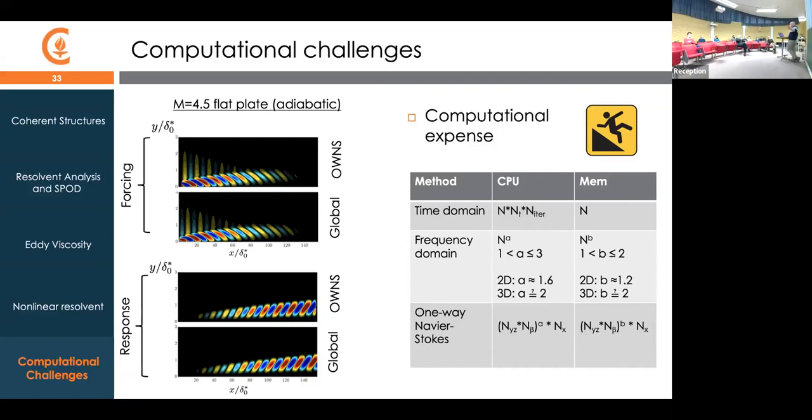These are space-time modes from the full space-time correlation, right? I'm doing it in the frequency domain, but that's kind of irrelevant. These are the space-time coherent structures out of the full two-point correlation. So they do survive over a long time. By definition, they survive over a long time. They're more monochromatic and they are wave-like in time. They're one frequency at a time, because that's the optimal way to do it for stationary flows.